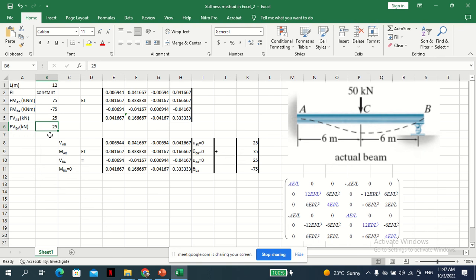All right. Now to derive the stiffness matrices, you simply substitute here like shown. So we ignore the axial parts which are not there. So we only end up with a 4 by 4 matrix as shown. So this, for example, 12 EI over L cubed is this value. You can see EI is factored outside, so 12 divided by the length cubed. All right. And the second value is 6 EI over L squared.